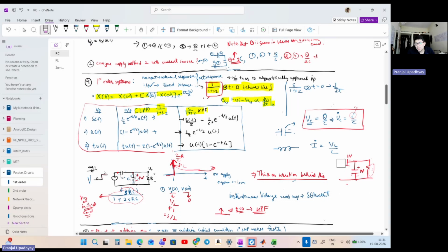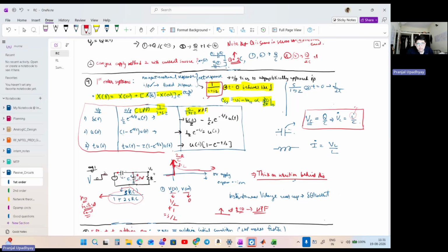So here, the important takeaway is that the main culprit behind this impulse was also the initial condition, which prevented this capacitor voltage from changing suddenly. And because of that, we saw this impulse. But again, the safest route would be to solve it mathematically and then come to the conclusion that this is happening. This was just a way to gain an intuition as to why the circuit behaved the way it did.